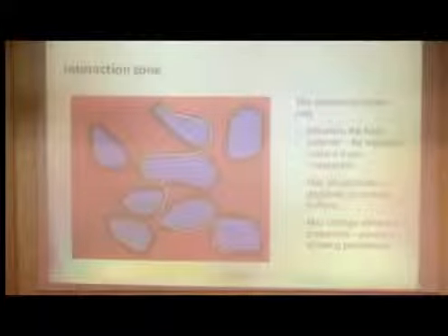So these interaction zones, as I said, might make it more crystalline, or they might not. They might attract water. I'll tell you about that a little bit more. They might change the dielectric properties, perhaps allowing some sort of percolation, electrical percolation, perhaps between these various interaction zones. Only a small concentration of particles are actually required to approach the percolation limit.